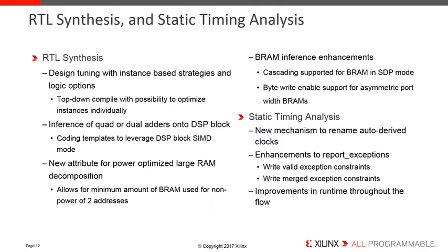In static timing analysis, there's new support to allow renaming of auto-derived clocks, clock domain crossing waivers, enhancements to report exceptions command, and improvements in runtime through the flow.